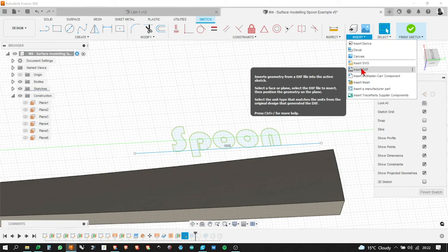What's the difference between a gap and a solid area? If you think about bringing in that sketch, it'll understand whether it's a closed loop or not. If it's a closed loop, it'll see that as a closed loop. If it's not a closed loop and there's a gap in your original Illustrator file, it won't show that pale blue, if you remember those closed loops. So if it's correctly drawn, you should be able to pick the bits you want to extrude. But you've got to do it accurately in Illustrator.